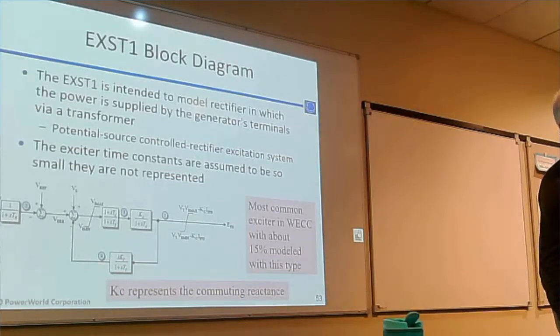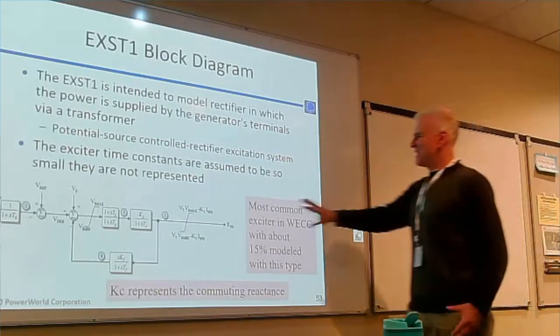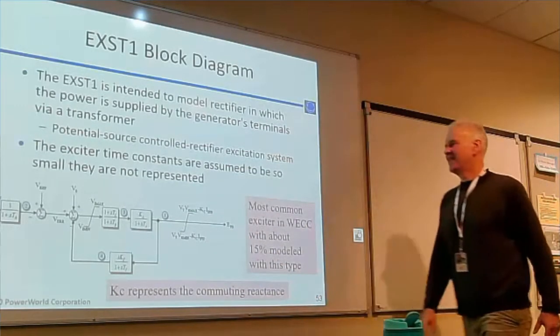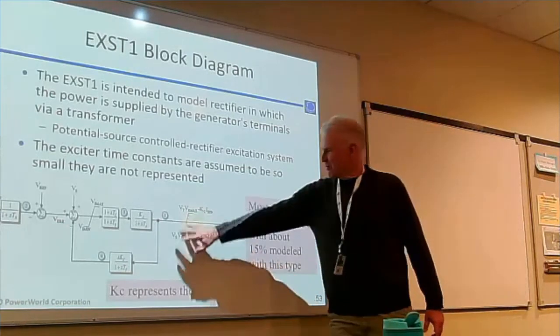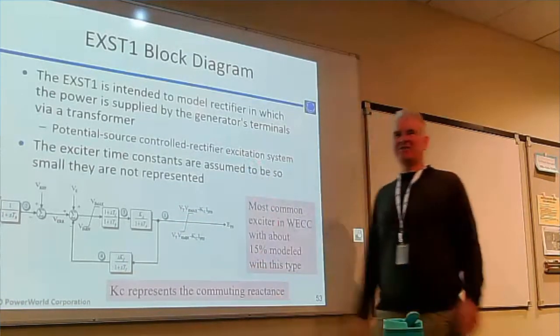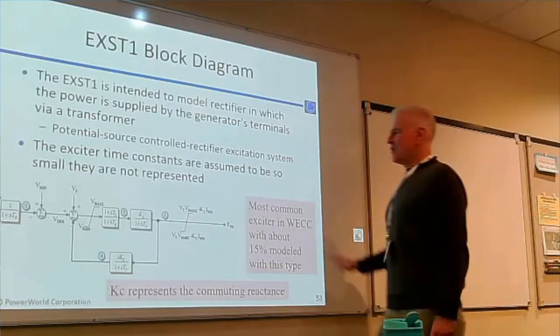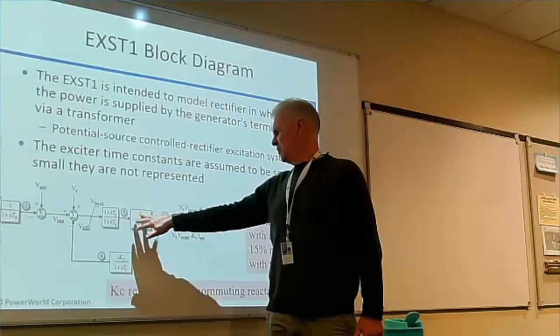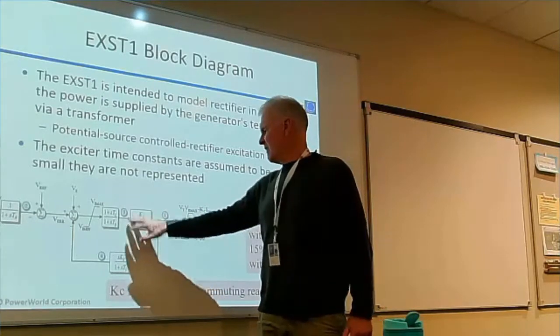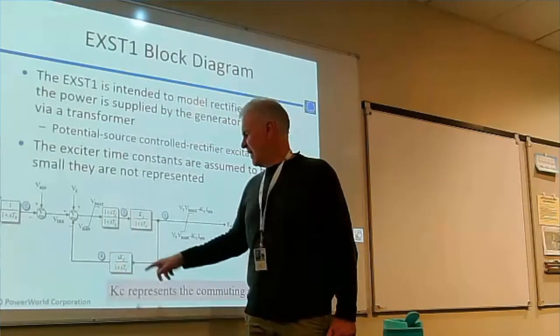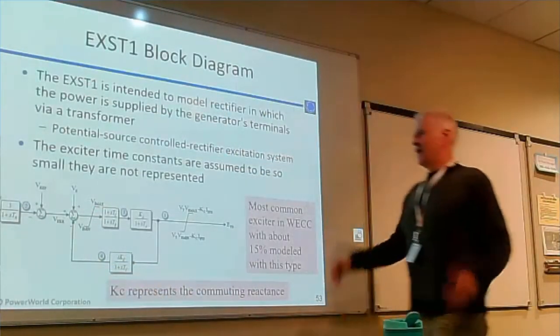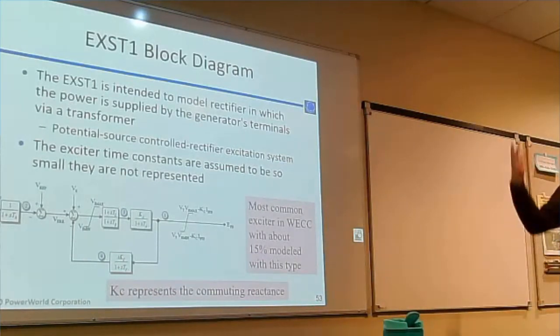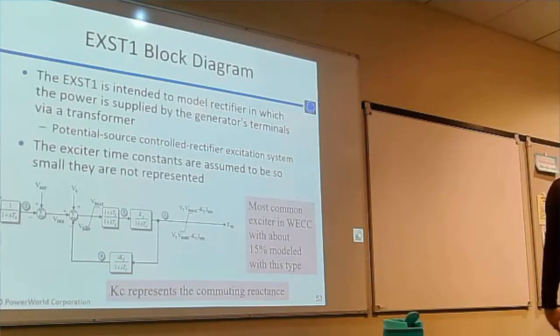Yeah, none of that machine junk. That's all gone. I mean, it's saying it's so fast we just get rid of it. We just pretty much represent it with limits here. It's so fast you're not worrying about it. So you've got just parameters that you're sort of setting. There's the voltage gain, the TA value on your amplifier, the lead lag there, the feedback circuit. That gives you a very fast and controllable device.